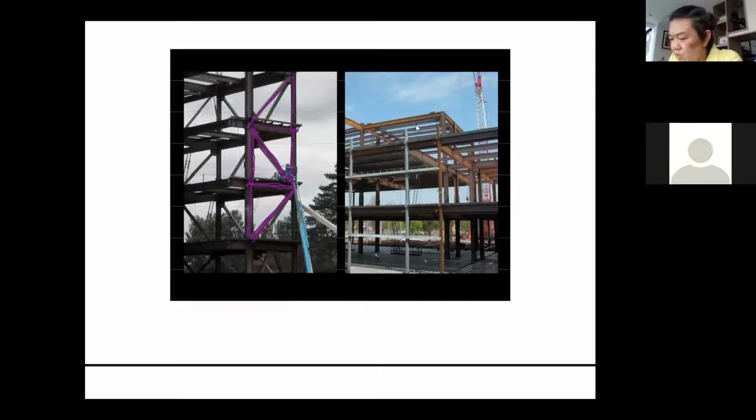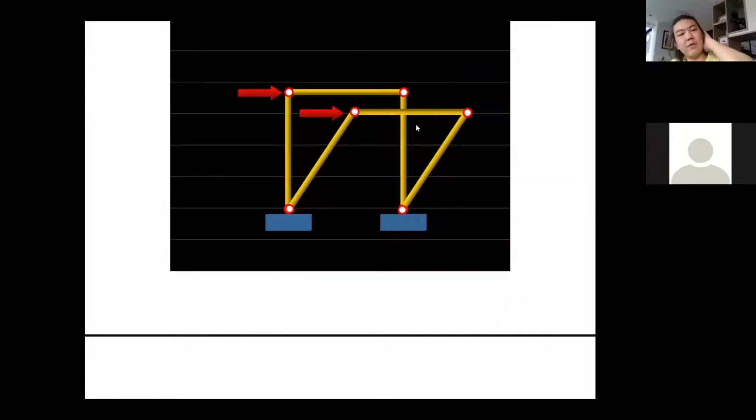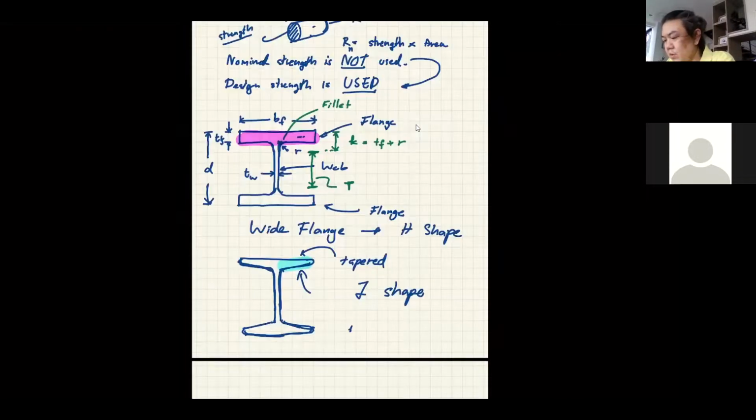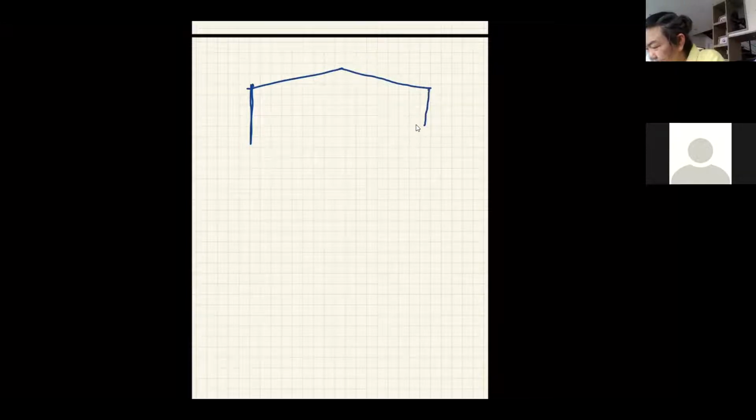If you cannot have the brace system, you need to make sure that your frame here is strong and can take the moment, meaning that this better be a rigid joint just like in the frame. So this is the main reason why we have to study the frame in the structural analysis class. And this is a very important concept, because generally if you have to deal with the frame of a warehouse or a factory, this is what you can commonly have. Because in a factory you need a lot of space between them, right? It's going to be a very, very wide system, and it goes in that direction. You have so many frames in the longitudinal direction.